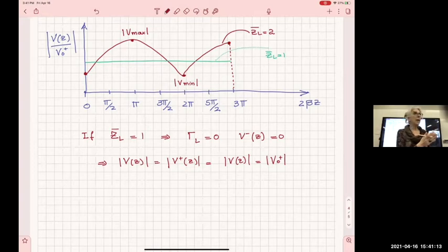So that means that I have spent a lot of money to generate power at 5 gigahertz. So for a 5G, you spend a lot of money to generate that power. So the worst you can do is to reflect it away from the load. Your load is your antenna, for example. Usually antennas, when they operate at the center frequency, are resistive. They have a resistive value.